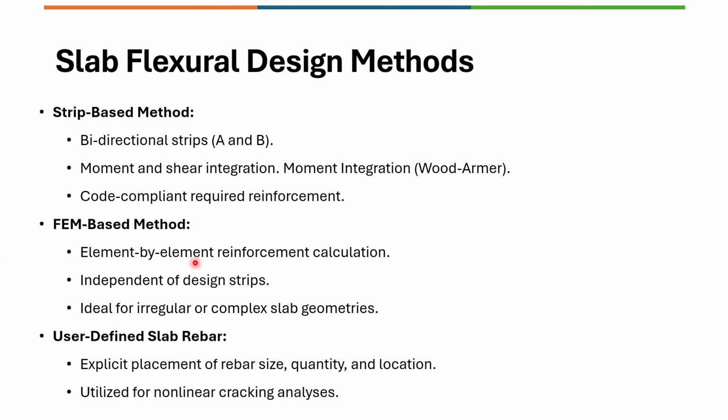Within the slab flexural design method, this program performs by default the FEM-based design, which is always available to you. But our recommended method would be the strip-based method. So bidirectional strips have to be drawn, and then the moment integration will be done for these strips. They will be used as the forces for the design, and the design procedure will utilize the requirements based on the code